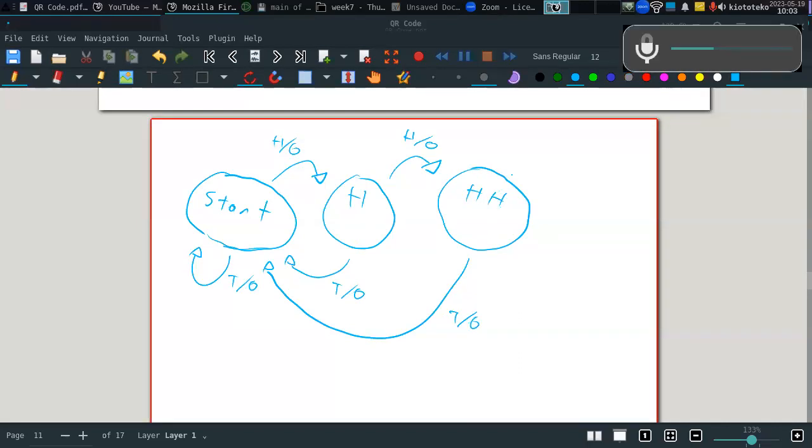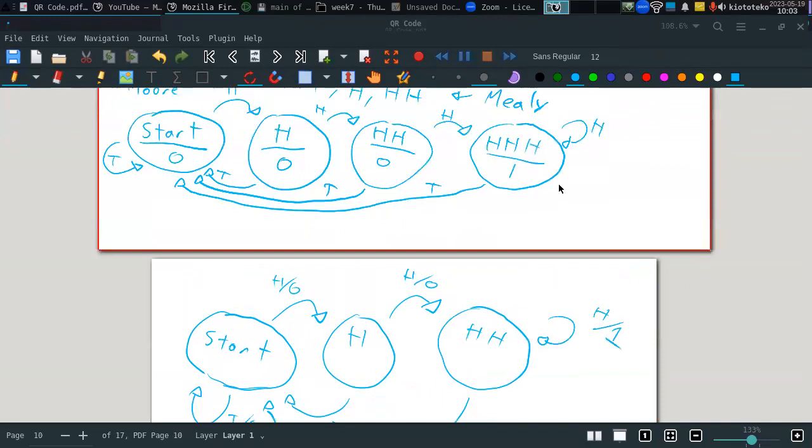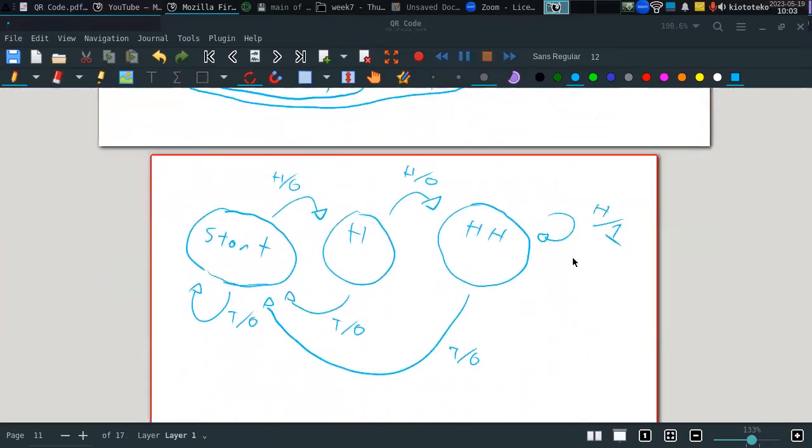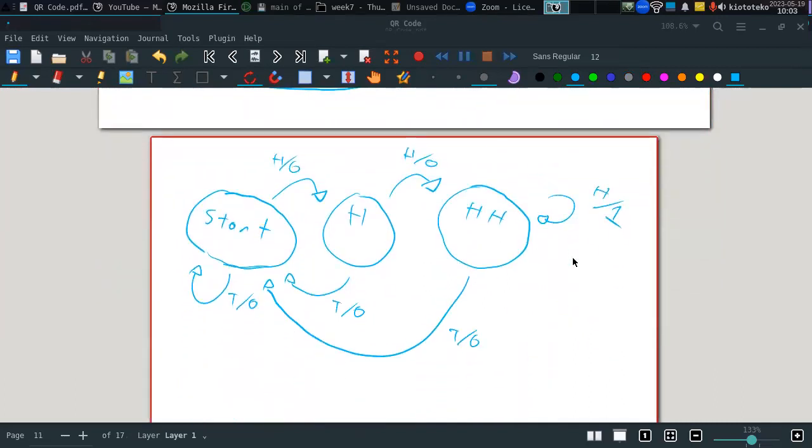for example, we need another head, but we need to point it to another state. Well, we could do a third state, but I guess if we want to do it cyclically, we could just do this, no? It's 1 if we want to express it the same as here. So yeah, this would be a similar solution to this, but with only 3 states and with a Mealy machine. Does this make sense?